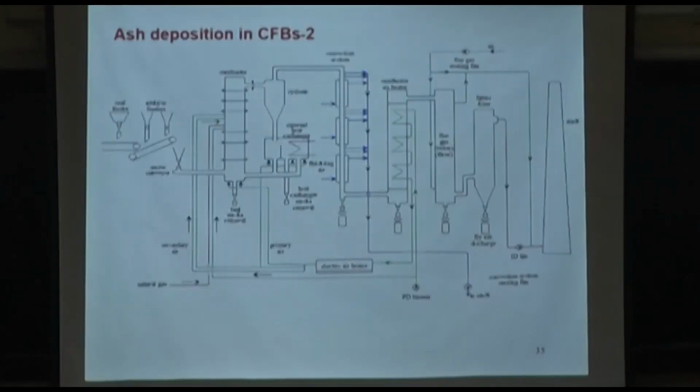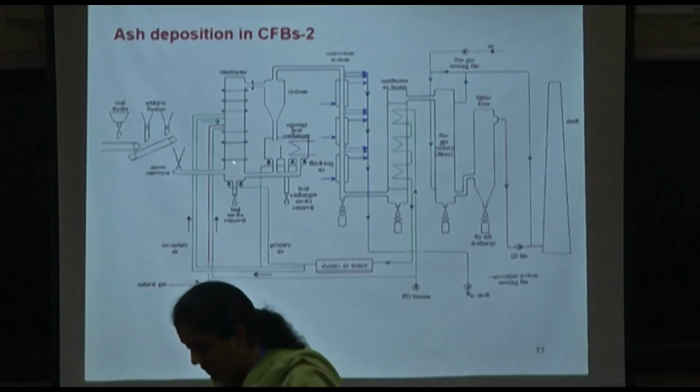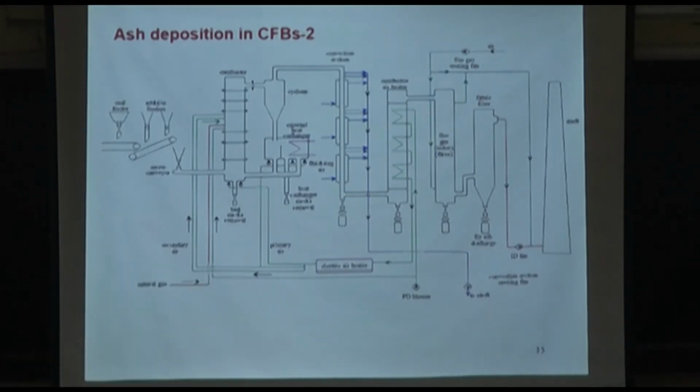So this is one of the schematics of a fluidized bed combustion pilot plant, the first one in Australia that I had the opportunity to commission and then run over a substantial period of time. It's not a huge one, it's only 100 kilograms per hour coal feed. This is the main combustor, about 7.2 meters tall. The internal diameter is 450 millimeters.